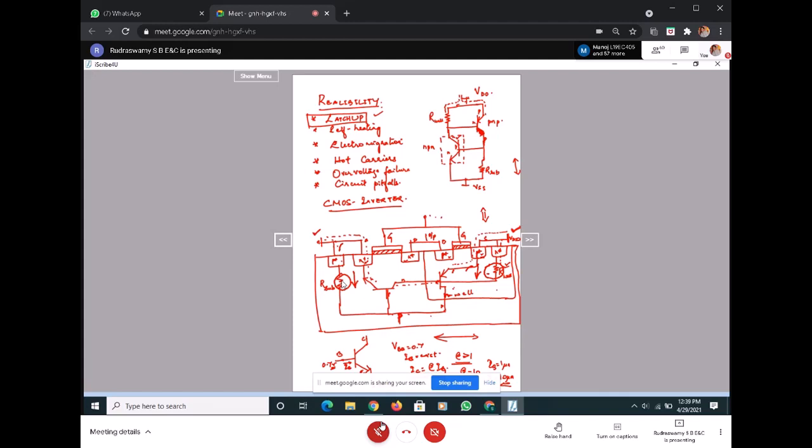This is what is all about the latch-up problem that exists in an IC, especially in terms of the CMOS inverter. The CMOS inverter is the basic building block for any of the MOS circuits, right? And that's why they ensure that the latch-up problem is overcome. So this is what I wanted to tell you after the interconnects, that is the reliability aspect, that too of the latch-up problem.